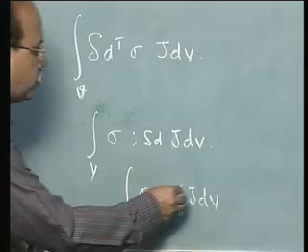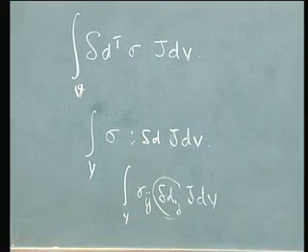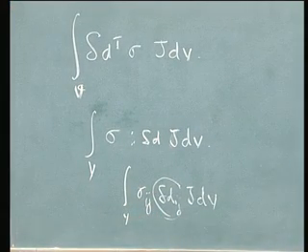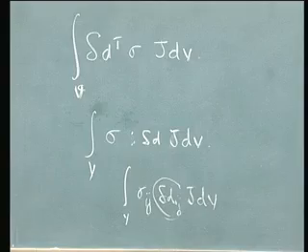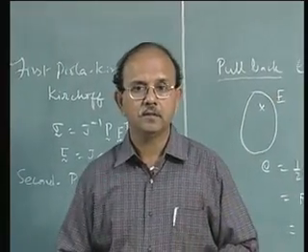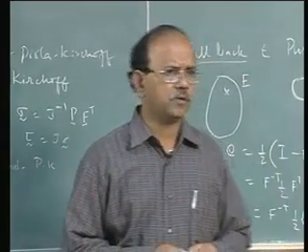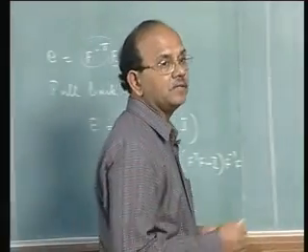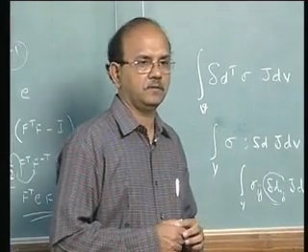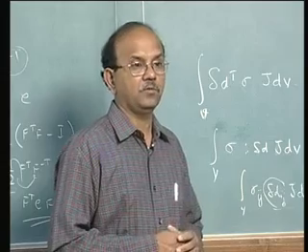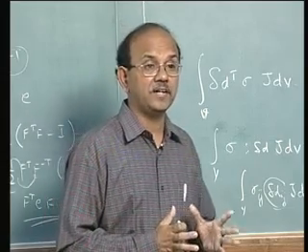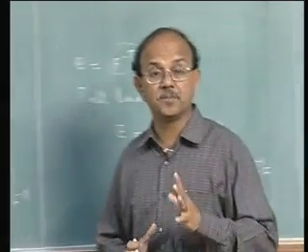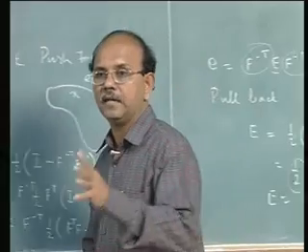I have to replace this quantity. What is this quantity d? Yesterday we saw that, right? I used the symbol d only, if I remember right. Please have a look at that. Yes, rate of deformation tensor. What is the rate of deformation tensor? That is the symmetric part of L.